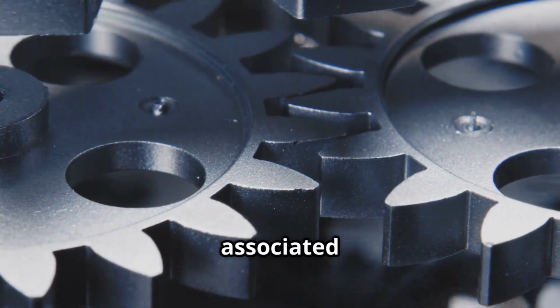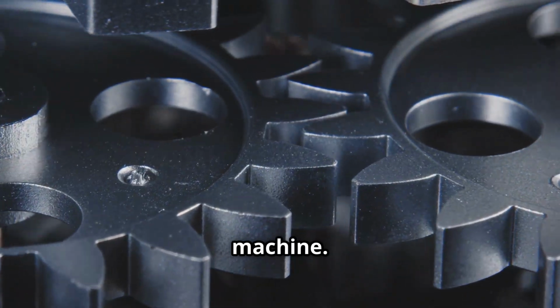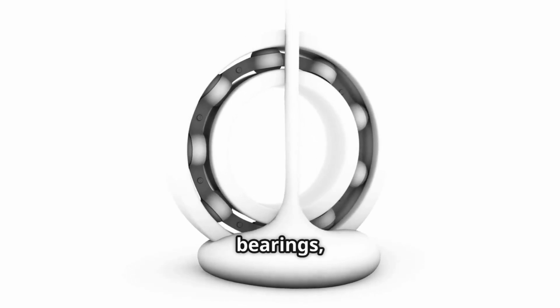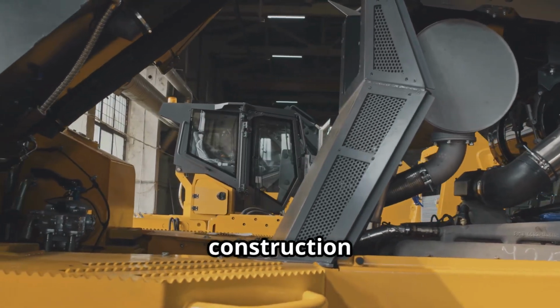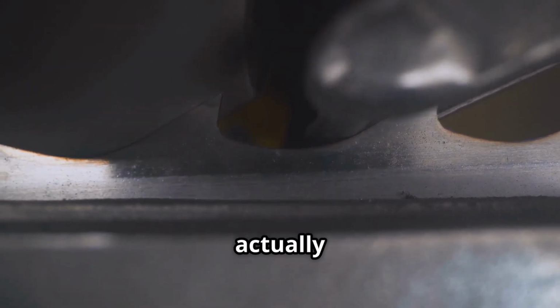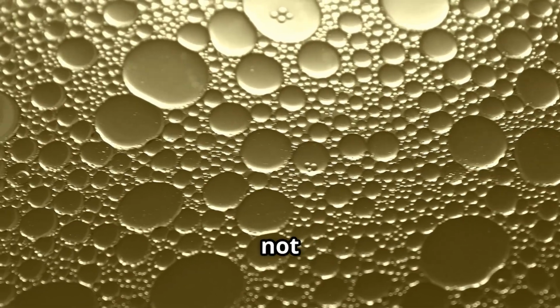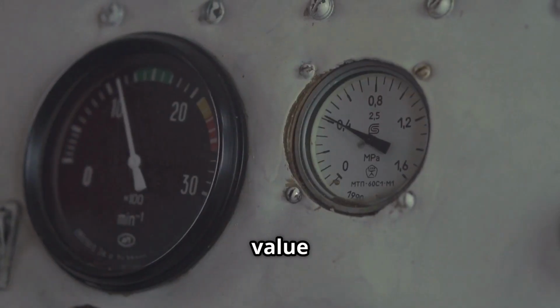Boundary lubrication is associated with metal-to-metal contact between two sliding surfaces of the machine. During initial startup or shutdown of some equipment like journal bearings or under heavily loaded conditions, such as pins and bushings of construction equipment, the metal surfaces in a lubricated system may actually come into severe contact with each other. If the oil film is not thick enough to overcome the surface roughness of the metal, a lambda value of less than 1 results.